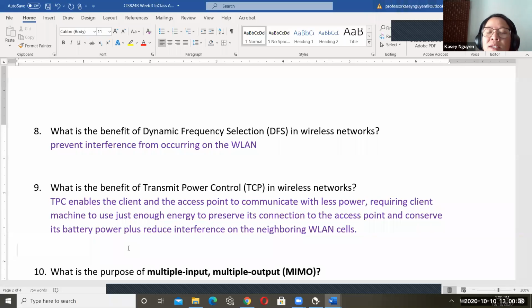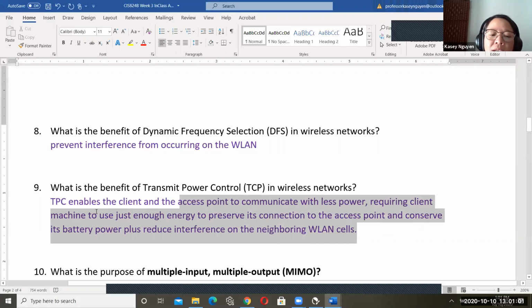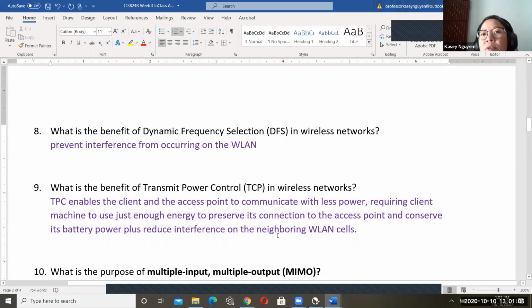Because if you have antenna sticking out, people might tamper with it, it might cause corrosion. So in some of these boxes, what they do is they have antenna that's incorporated inside the housing of the actual component. So with those, it would be better to implement transmit power control. Okay.